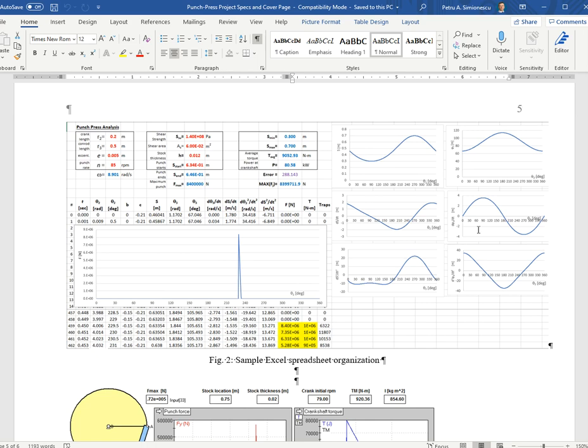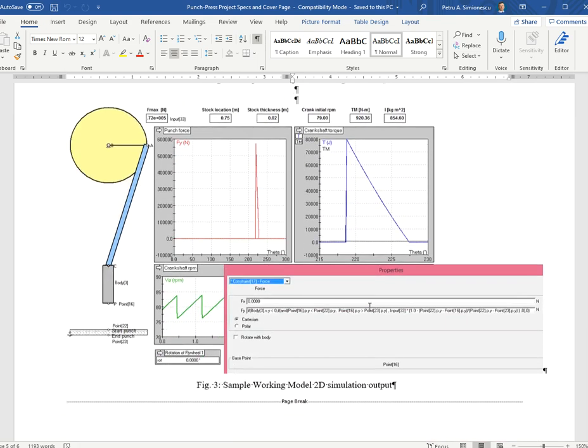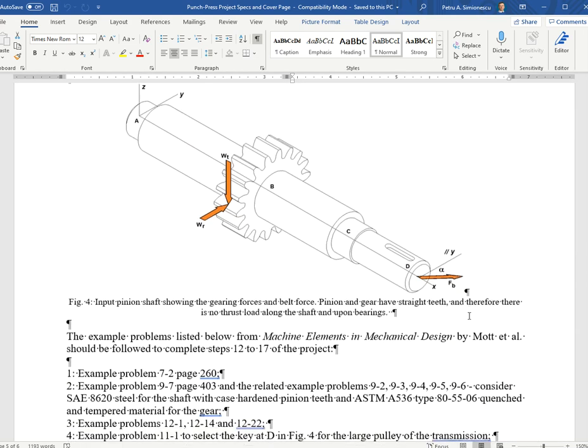Same for the theta 3 angle, so you again have theta 3 dot, theta 3 double dot. A quick way of checking for correctness is to have velocity going to 0 where you have the limit positions, and acceleration going to 0 when you have minimum and maximum velocities. Likewise here, a known thing: the derivative goes to 0 where you have a minimum or maximum.